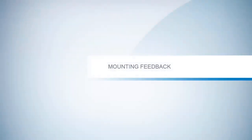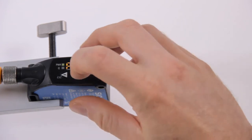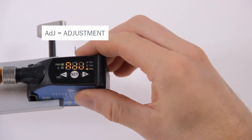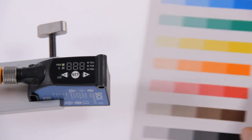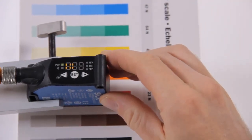Mounting feedback. The mounting feedback function is available by default for the very first setup of the sensor. At a later point of time, this feature can be selected manually by using the plus and minus buttons to navigate to ADJ for adjustment. Confirm the item with Set. Now the adjustment can be done observing the bar graph. When the adjustment is finished, confirm with Set.